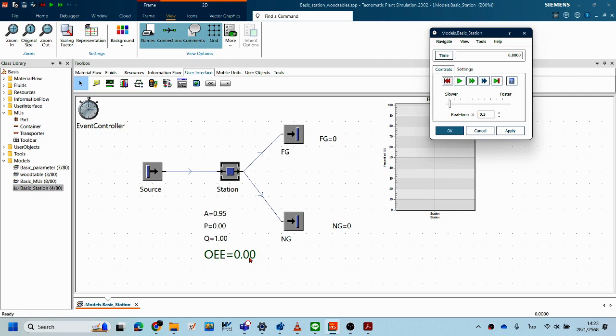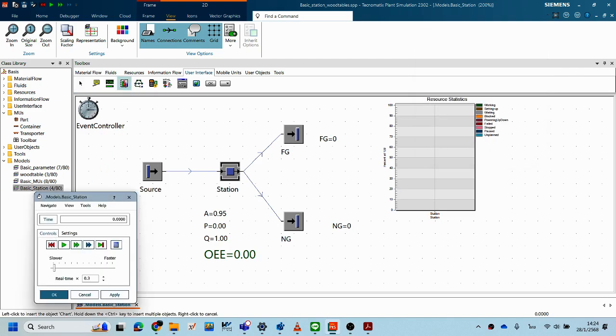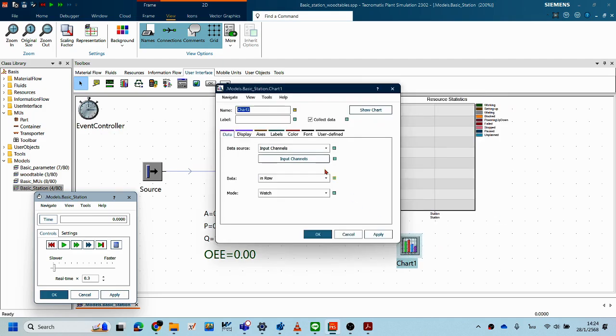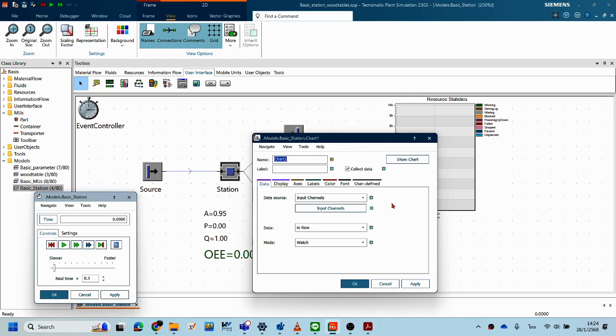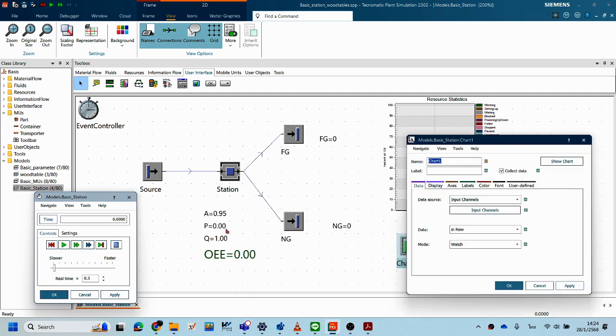dynamics movement, right? It's a real-time movement during the simulator. It's running in your process, and the OEE is running, right? The real time. You can plot the trend of the line graph, right? Of the OEE value. Okay, I use another chart, got to here about here. Okay, double click on this. Okay, right now I need to show up the OEE chart and